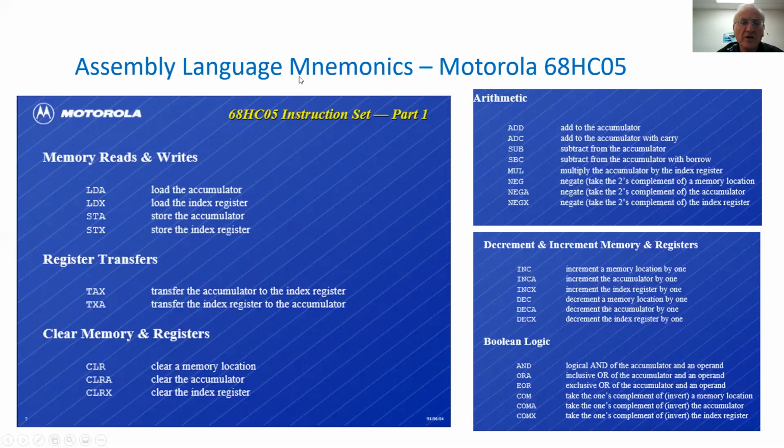The mnemonics for the assembly language are specific for the particular processor or microcontroller that we use. This particular one is for Motorola. And we see, for example, LDA is used for load the accumulator. LDX is load the index register. STA is store the accumulator. STX is store the index. Then we have register transfer, TAX and TXA.